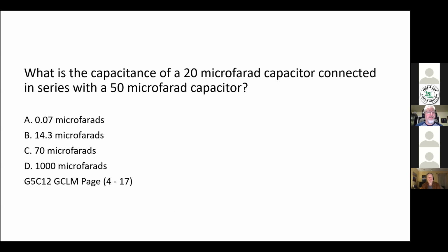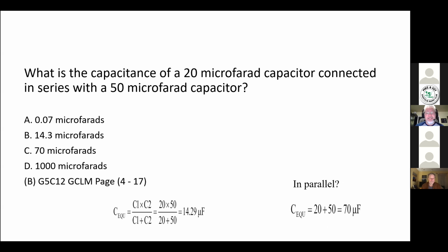What is the capacitance of a 20 microfarad capacitor connected in series with a 50 microfarad capacitor? Here's your answer now, that's the B. You just did that one, 14.3. When you do the inverse or reciprocal situation, you're looking for the number just below the smallest value. That's a fast way to double check your answer.